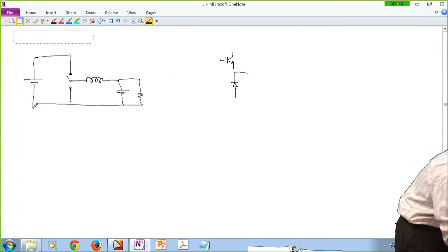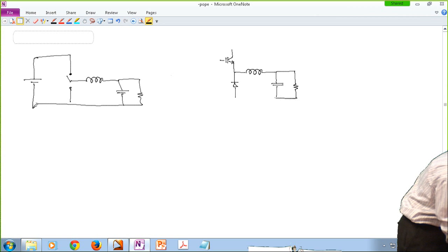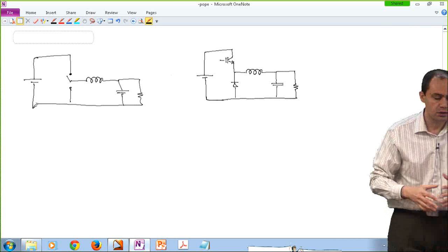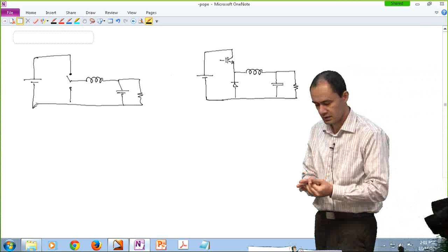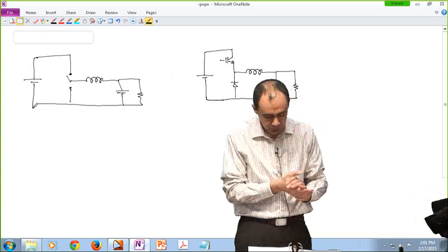We looked at the voltage drop of each individual single pole, single throw switch, and also the current that is passing through that switch. Then we looked at the available products, which are diodes and IGBTs and MOSFETs, and realized that the top throw switch is an active switch, like a MOSFET or an IGBT, and the bottom one is a diode, which is a second quadrant switch.